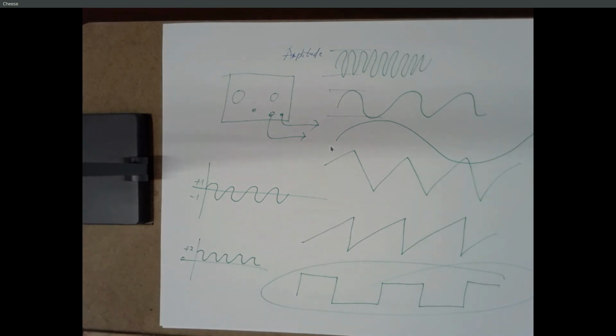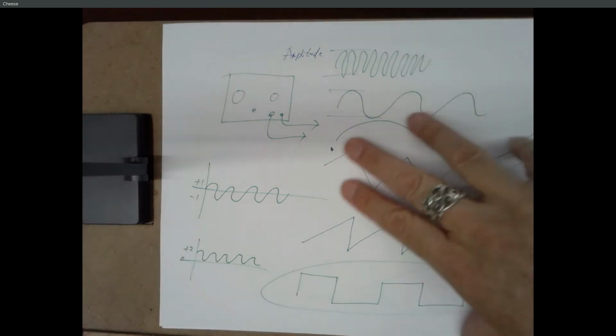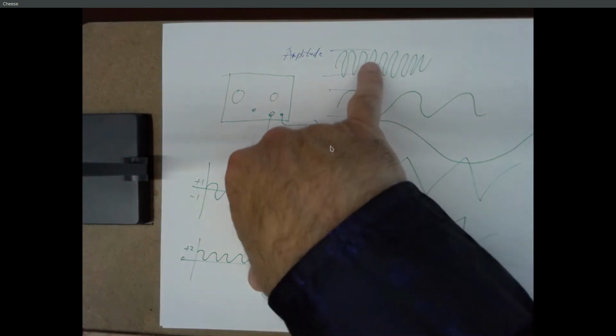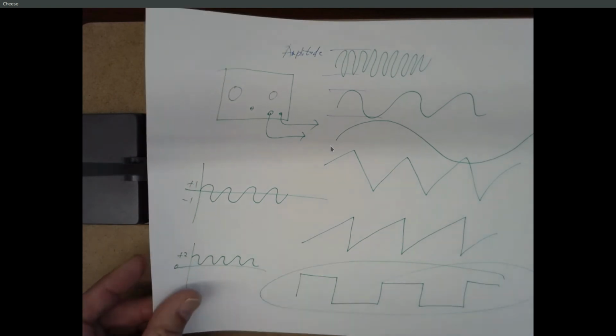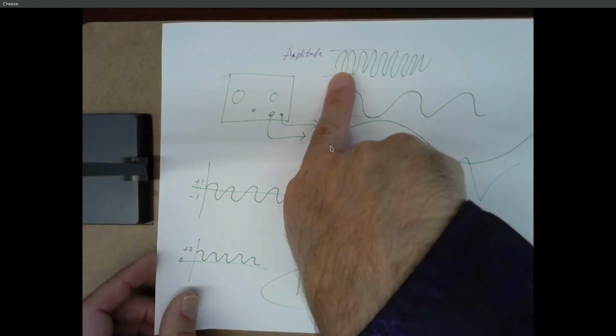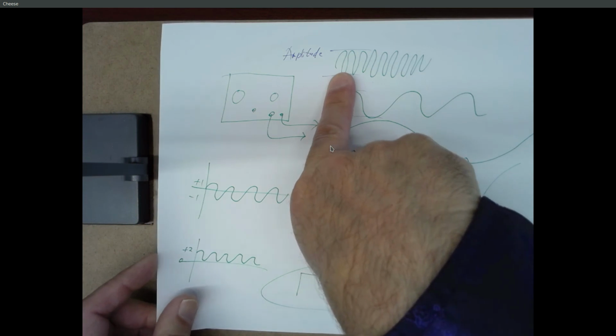Okay, so function generator is just a box that makes all these different types of waveforms, lets you control things like frequency, amplitude, and so on. A multimeter will not help us in looking at these waveforms, because if you hook this up to a multimeter, your display just changes numbers rapidly. It'll show 0.7, negative 0.2, negative 0.6, 1.3, and it just bounces around a few times a second. So an oscilloscope is a device that lets us look at these waveforms basically by drawing them for us.